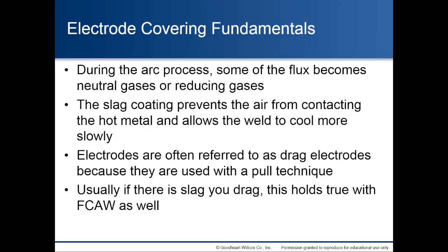Electrodes are often referred to as drag electrodes because they are used with a pull technique. Usually, if there is slag, you drag. This holds true with flux cored arc welding as well.